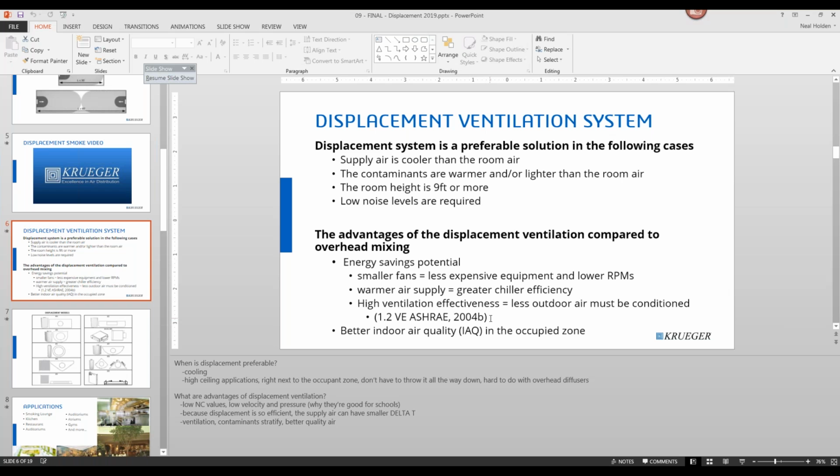I have never seen the fire dampers placed directly at the inlet. So you can place them in the ductwork, but I haven't seen anything that's placing them right in the ductwork that's penetrating into that room space. So I have to assume that they're above the ceiling. Yeah, they're generally at the penetration into the space.